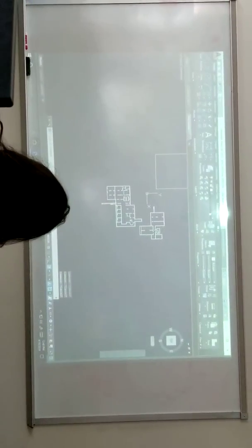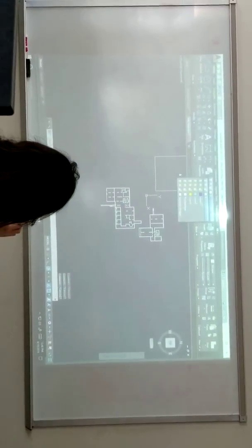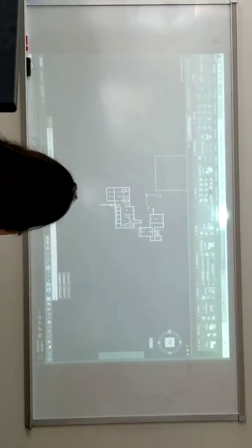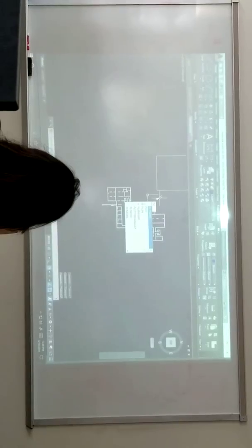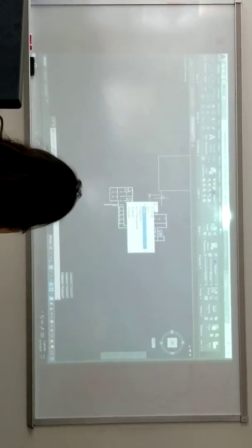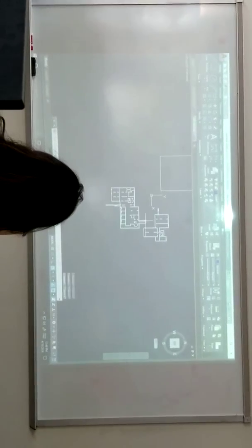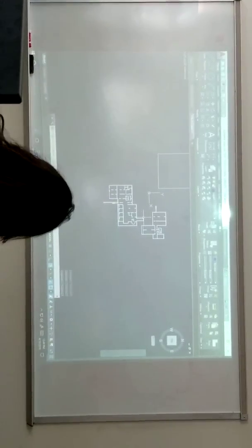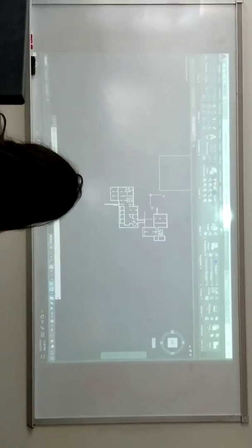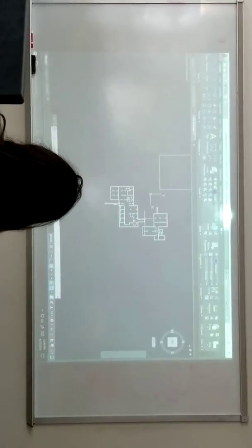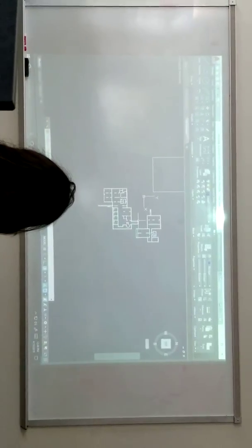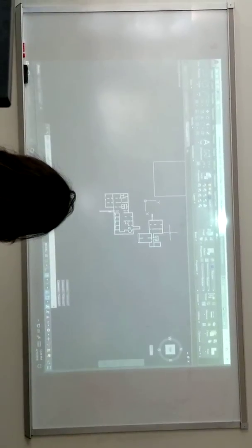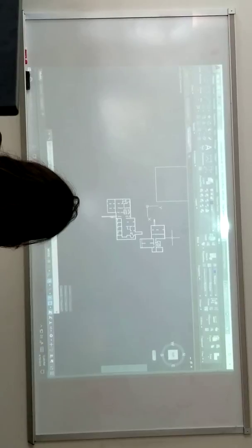If I want to draft under a certain layer, up here under my layer properties area, I say, all right, I want to draw only under layer 1. So I'll go around and say I want my outline, because I know that's going to be my thicker line weight, out at the boundary. So I want that to be blue, because I have blue set as my thicker boundary, or I will when I put it in Illustrator. I'm going to create a line, but I'm not just going to type line. I want to type in polyline.